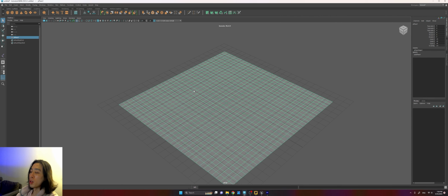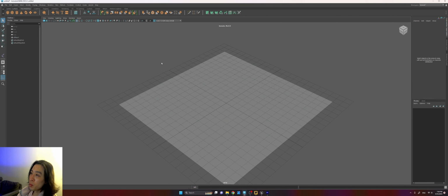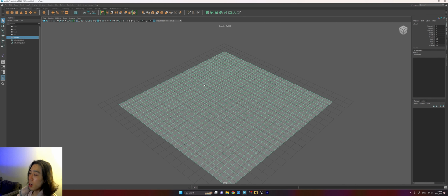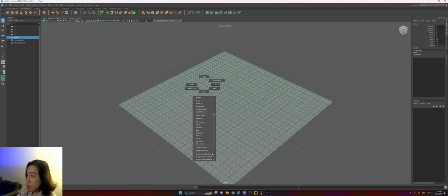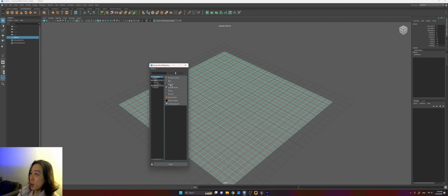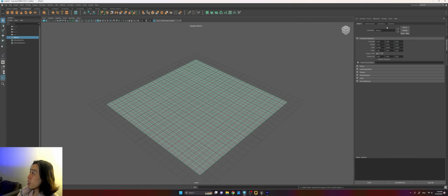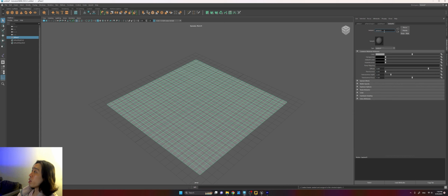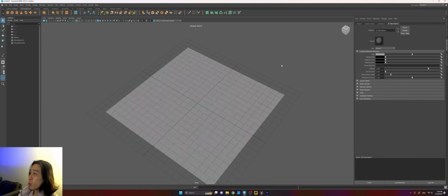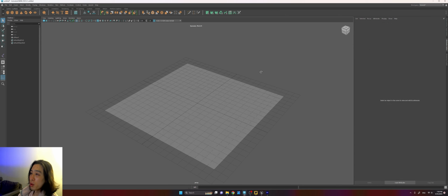The next step is to create a material. So we left click on the mesh, right click, assign new material, and then we hit Lambert as our basic material, and we can see some of the bar pops out, and we go to Lambert 3, rename it into material underscore plain fabric, and we have our basic material ready.